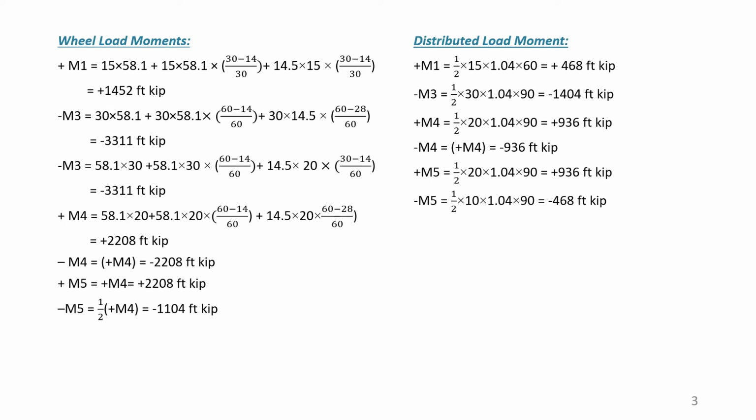If we put a wheel at 0.6, there will be 0 moment, and at 0.3, the moment will be 0. If we put the load at the tip of the cantilever, that is 0.2, there will be a reaction at 0.6 of 1/3, and if we multiply this by 1/3 into 60, that is 20.